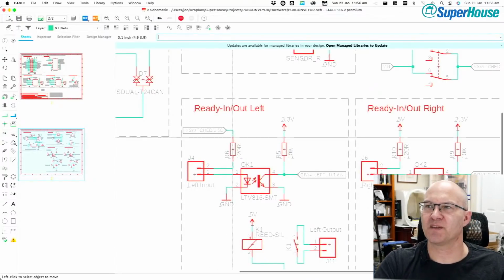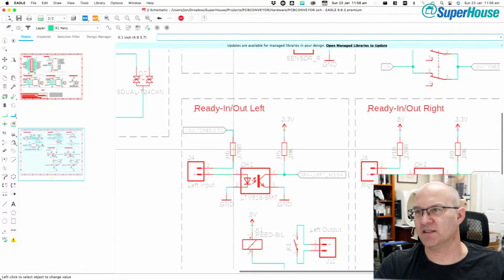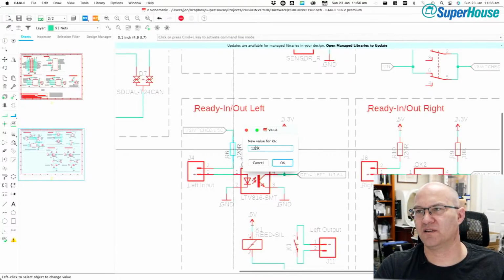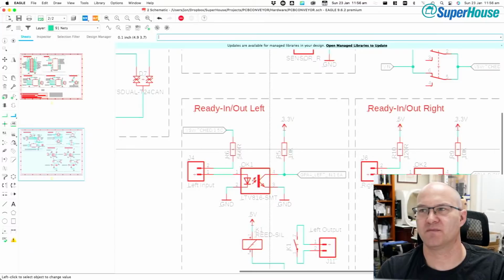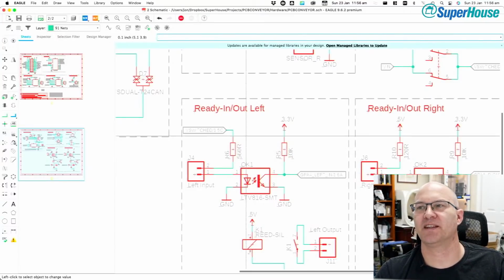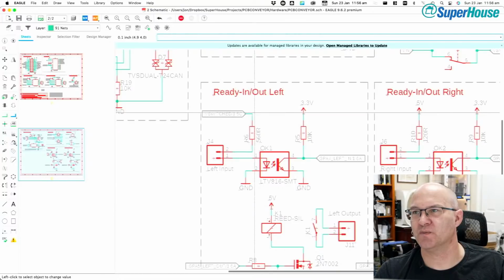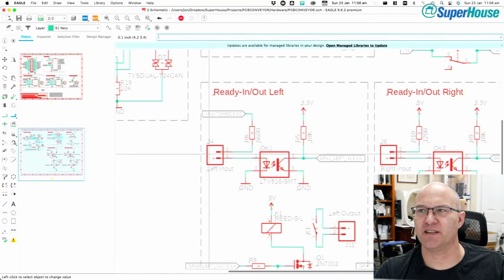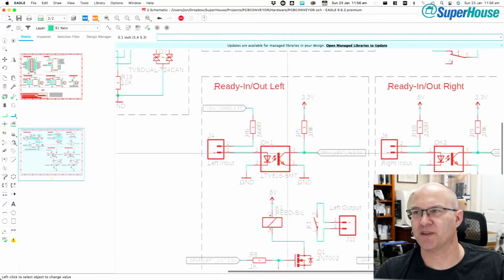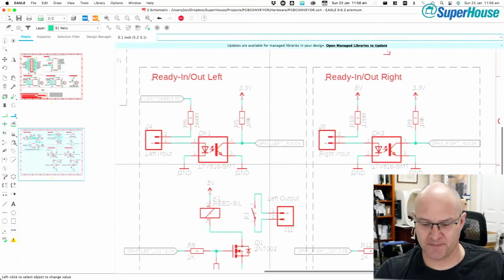Whatever is coming in would run through this, and I'm going to have to calculate the value, but let's make this, I don't know, what would it be? 560 ohms, give or take? I don't know. I will figure that out. But anyway, what we would do is be taking the switched input voltage and then feeding that through. So effectively it'll be getting like 24 volts coming back out here and coming in through the Opto-isolator. Yeah, overall I think that is better.